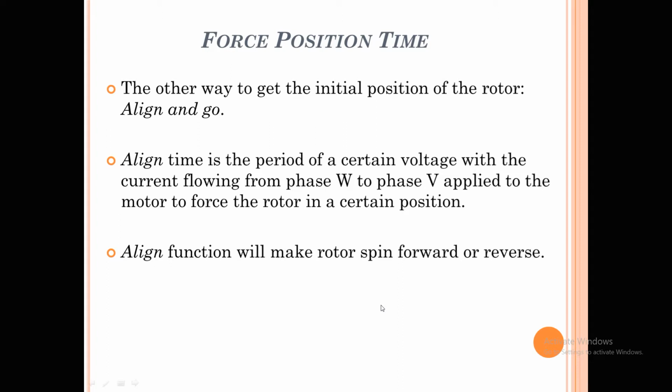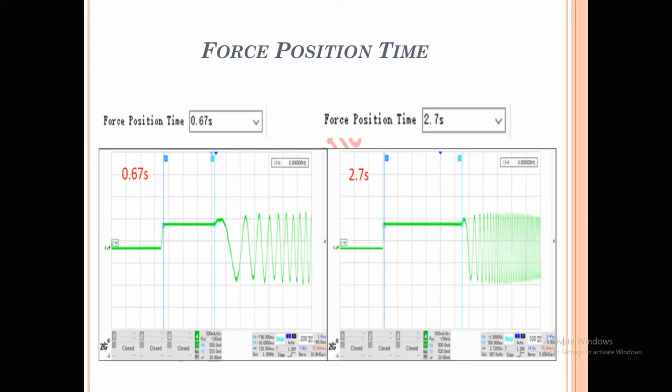If you select a very short time duration, it may lead to startup failure. So we need to select this time as large as possible, but not too large, because with a higher value it will take more time to start. So we need to select a proper value based on the physical characteristics of the motor, so that's totally a dependent factor.